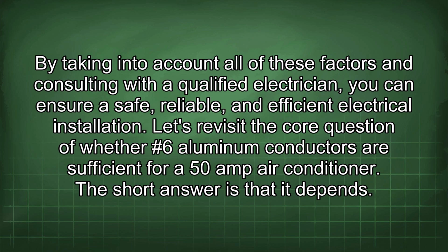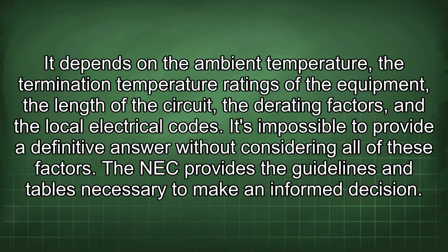Let's revisit the core question of whether #6 aluminum conductors are sufficient for a 50 amp air conditioner. The short answer is that it depends. It depends on the ambient temperature, the termination temperature ratings of the equipment, the length of the circuit, the rating factors, and the local electrical codes.